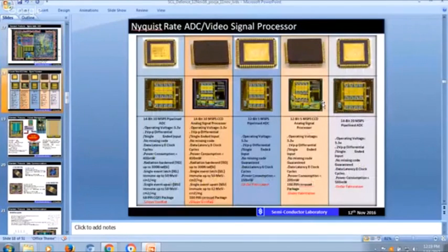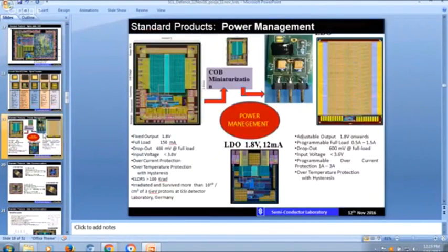Now I will show you this. This is again a voltage regulator, and this is a power MOS. It gives 150 milliampere of current. It's one transistor but with multiple fingers, many fingers, so that it is able to give 150 milliampere of current. And this is a single power MOS which can give 3 ampere.